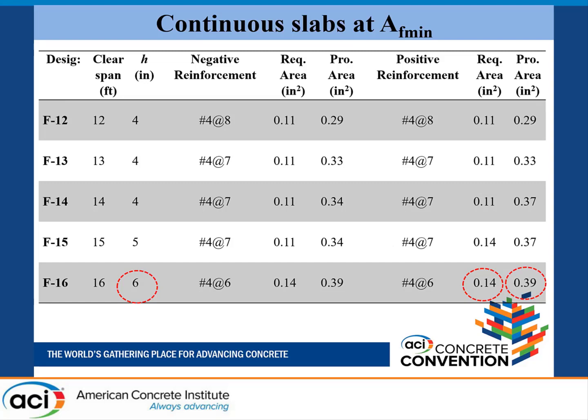This is because the ACI 440 guide says that you have to provide more reinforcement to control cracking. You can provide reinforcement to a maximum spacing, but in satisfying that limitation, you are actually providing more area of reinforcement. I don't know how they calculated that spacing, but it really hurts, even if you are using number 4 bar.